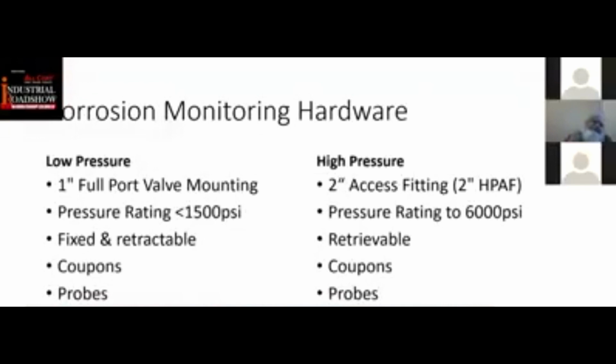At this stage, I must make it clear to the audience that pressure rating is a technical term that determines where you can use the low pressure access fitting or where one can use the high pressure access fitting. In fact, this is only one issue. The second issue is the convenience and the obstruction. Now, these low pressure access fittings are longer than the high pressure access fittings, so they can extend to a size of about half a meter to 1 meter.